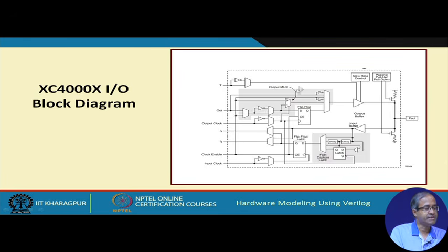So, the IO cells are also quite complex, as you can see. In the IO blocks, there are latches, flip flops, IO pads, tri-state controls, buffers, pull ups, there are a lot of things. Again there is some SRAM inside, and by loading it you can configure the output pins, whether it is an input pin or an output pin, whether you require tri-state control and so on, whether it is a strobed output, you need clock leading edge, falling edge, all these things you can program.